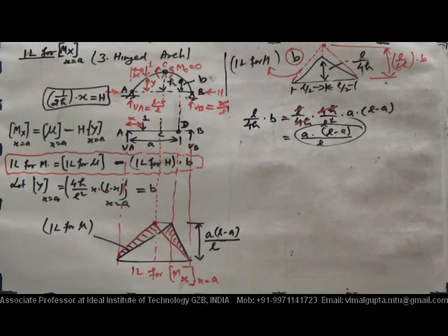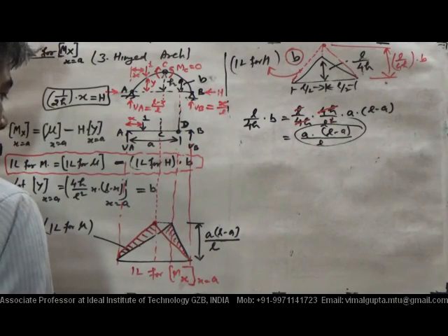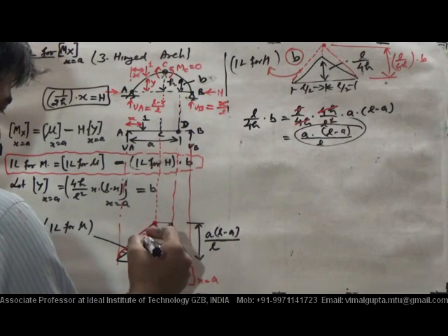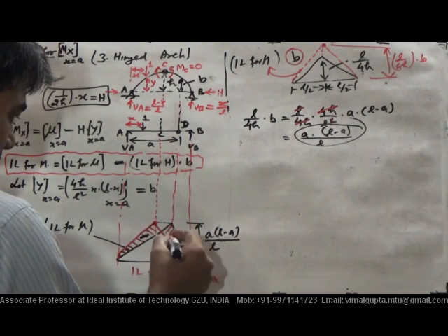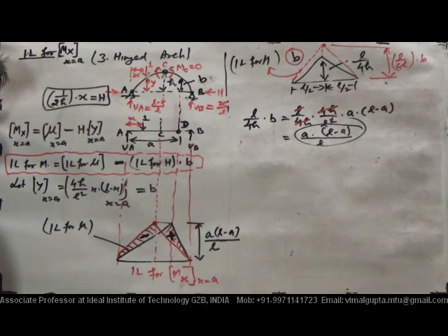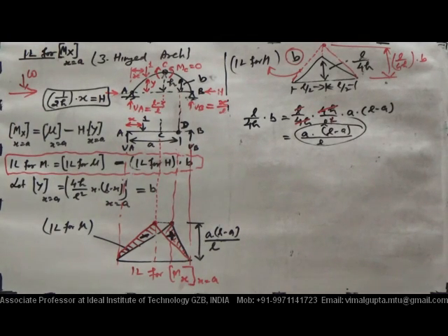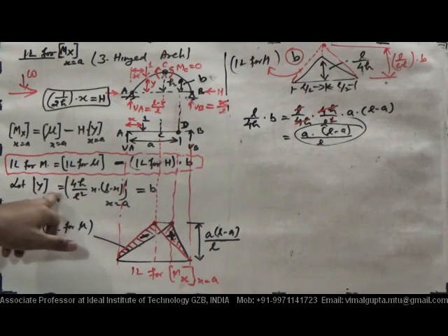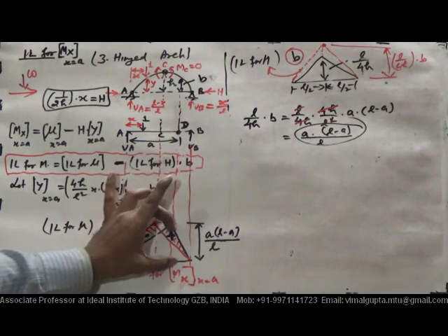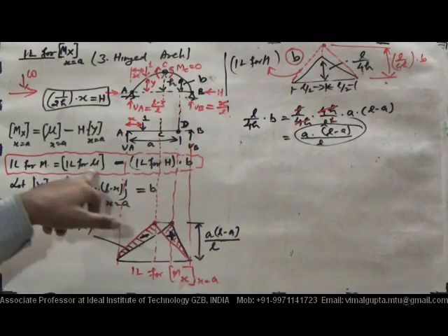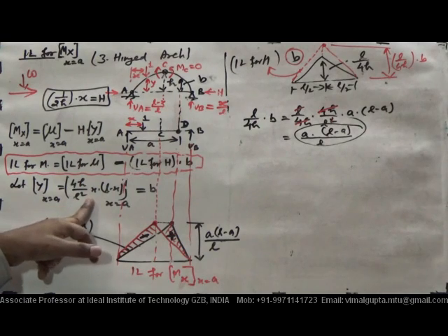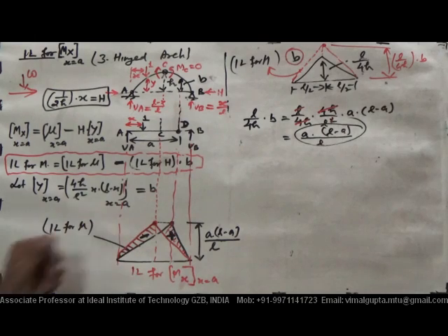Okay, what will be the sign? Which one will be plus and which one will be minus? Definitely this sign will represent minus, and this sign will represent plus. Therefore, if a point load W is moving in a 2-hinge parabolic arch, only for a 2-hinge parabolic arch, because why are we using a parabolic arch? Because we have used these ordinates, the same ordinates, for that expression, so it may not be true for a circular type of arch. It will be applicable only for a parabolic type of arch.